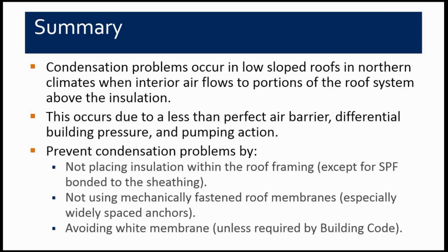So in summary, both of these problems are somewhat similar. They're both occurring in cold climates when interior air is permitted to flow above the roof system. In the case of the frame roof, there's an airspace above the insulation, which, again, if you do vent it, you're probably going to make things worse. If you don't vent it, there's still a possibility of air flowing in there because the system is not perfectly airtight, or it's very difficult to make perfectly airtight.